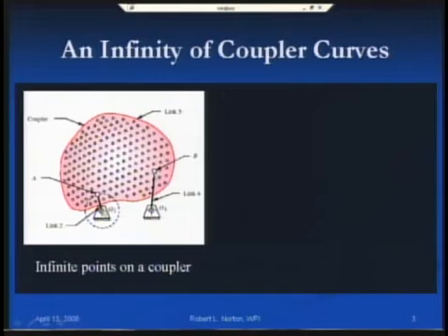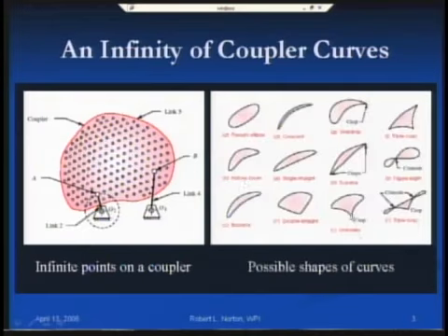Now we typically draw these links in the textbooks as lines connecting the points, and that may leave the student unaware of the fact that the link can extend in all directions to any degree and doesn't change the kinematics. The kinematic motion is defined just by the point-to-point lengths of the links that comprise the linkage. But we can extend those rigid body links in all directions as much as we like, which I've done here, and I've peppered it full of holes such that I could conceivably put a pencil through that hole, move the linkage through its motions, and it will trace the curve that we're talking about.